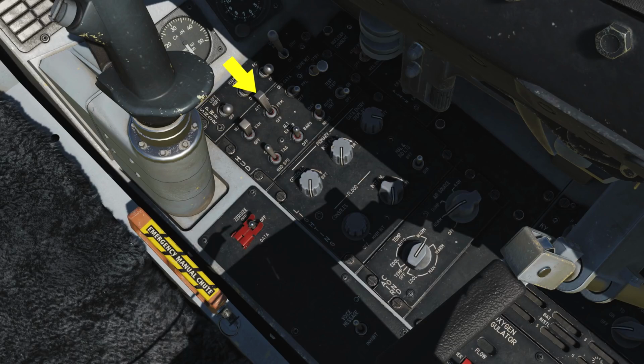The flight path marker switch, when set to ATT/FPM, displays both the flight path marker and the attitude reference bars. When set to FPM, it just displays the flight path marker. Off removes both. The DED and PFLD switch allows data from these displays to be visible on the HUD based on DED or PFLD selection. Now, off displays neither.